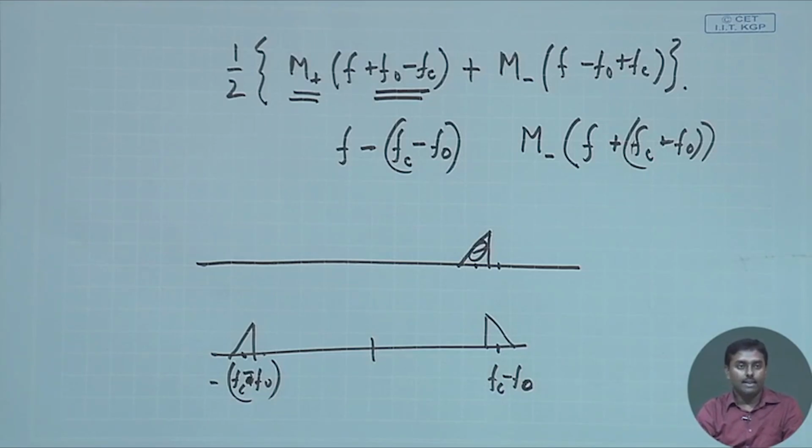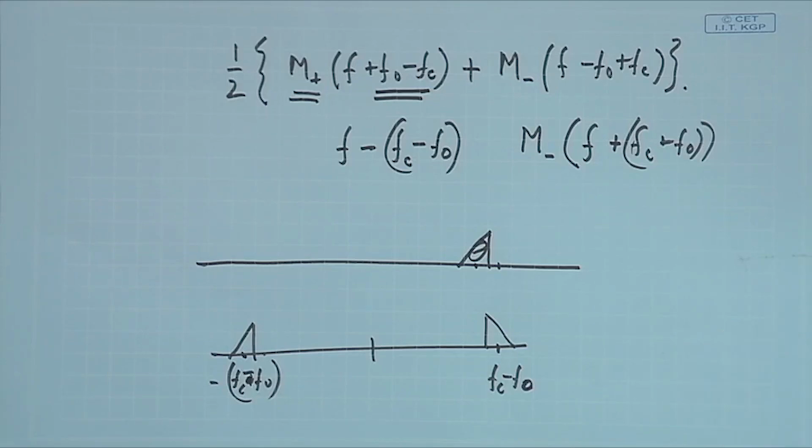So, you get a clear SSB representation, but you could see that we have never employed any Hilbert transform over here, it is just filtering. And that one filter that we have employed, where we can actually put a roll off, is possible provided there is that 600 Hz free zone. If there is no free zone, I cannot put that filter, because even a low pass filter at a very low frequency cannot get a sharp cutoff. There is no filter in this world which can have a sharp cutoff.